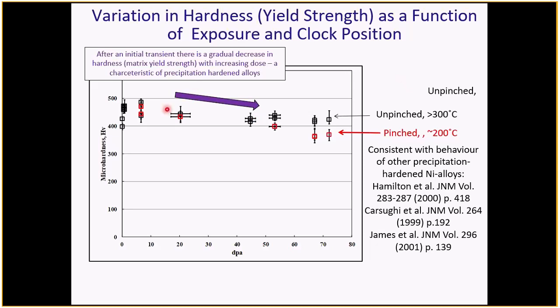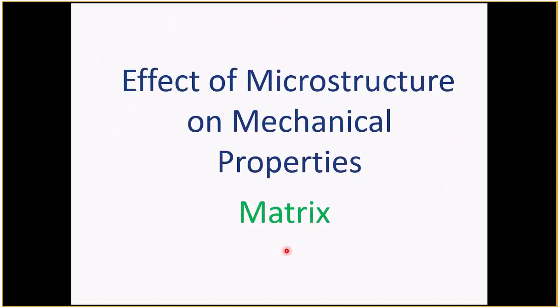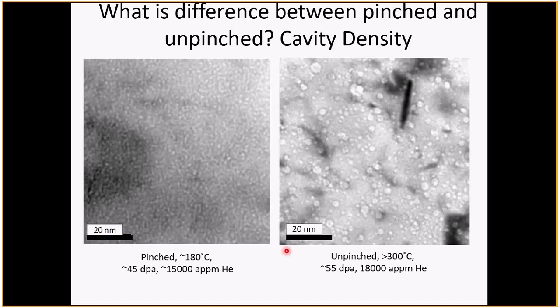So again, we have this process going on with this decrease in the yield strength. In this case, determined from microhardness. So the hardness of the material is a surrogate, another measure of the yield strength, against dose in dpa. I've talked about that, and I'll labor this again a little bit. I talked about the precipitates, but let's talk about other things that harden the material, clusters.